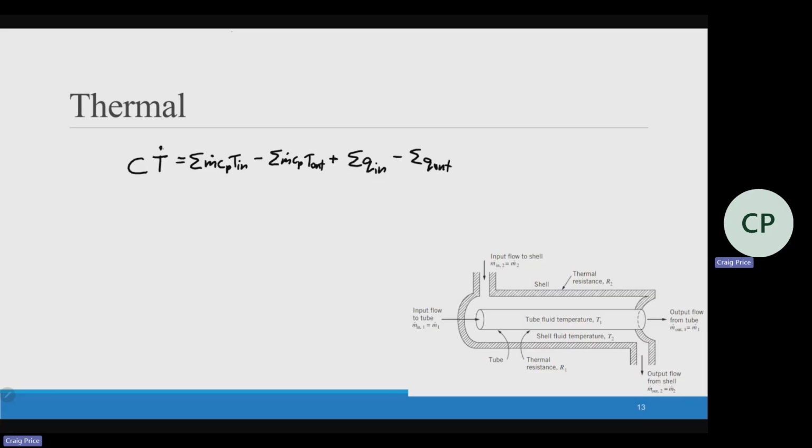And basically you just want to start here. You want to put your diagram together, show Q's. What I noticed was that for hydraulic and thermal, make sure if I've got a boundary or a resistor between two different parts, for every resistor, there should be a flow across it. It's uppercase Q for hydraulic, lowercase q for thermal. Any kind of resistance boundary, there should be heat going across it from one body to the next body. Does that make sense?